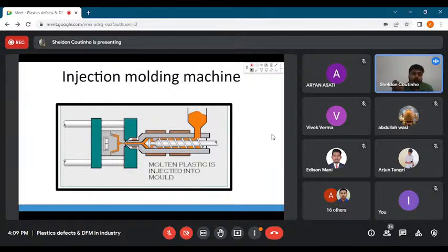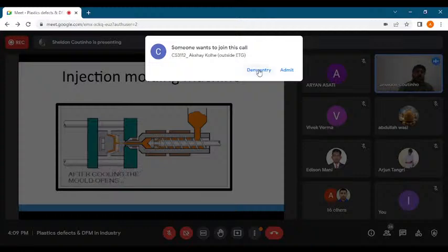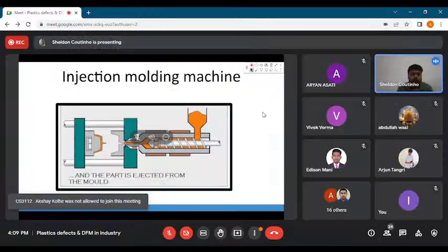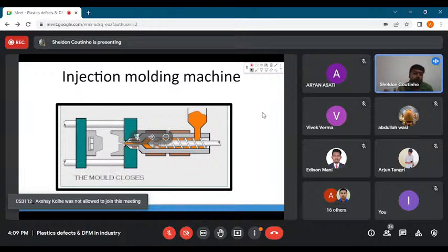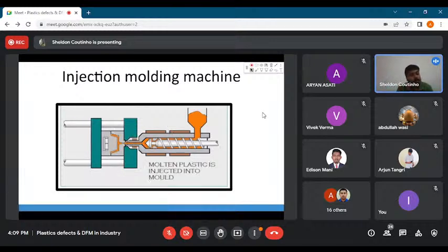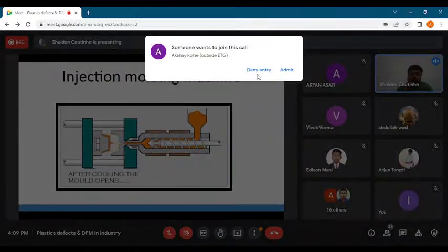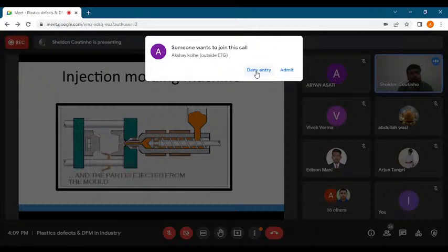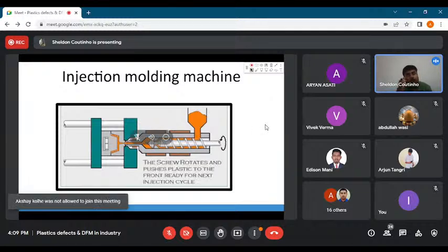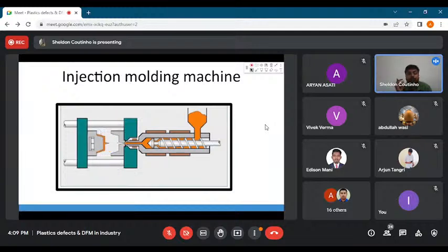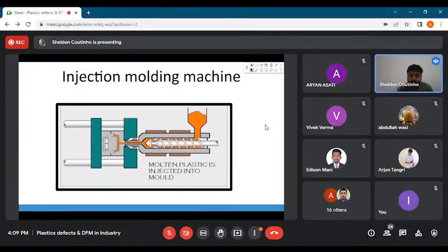But of course, we do not live in a world where calculations translate into the real world 100%. We will always have real world conditions. So what are real world conditions? They are basically that the mold is going to be a little cooler. When you start injecting the plastic into your mold, some parts will solidify quicker than the others. But while designing the mold and the plastic part itself, you have to make sure, and have that visualization, that this does not happen, because that's called uneven cooling. There are a lot of problems that come with uneven cooling, and that's exactly what we'll be discussing today.